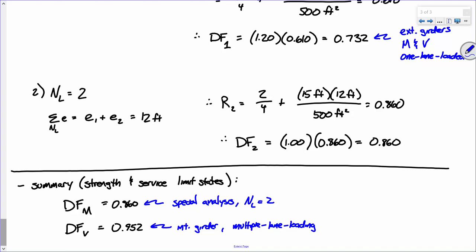Not too bad, right? Okay, now, we're not quite finished yet because we've got a little quandary with these values. Everything that we've computed, or at least most of what we computed, actually, no, it's not even most, it's a very small amount. But let me say this, all I can state definitively is that these are the governing distribution factors for the positive bending region. Okay? Why can I only make that claim for positive bending? Because earlier, what was the very first thing that we computed? Very first thing in all this.